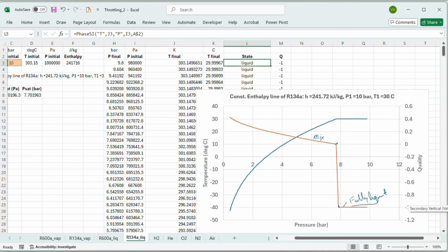of liquid and vapor, and the quality goes from 0 to a higher value. So that means it's evaporating. So when a liquid enters an expansion device, the drop in pressure quickly causes more liquid to evaporate, and now the drop in temperature is more dramatic.